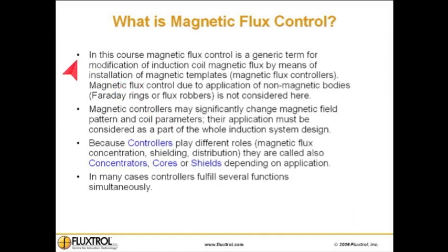Welcome to this section on magnetic flux control. First, what is magnetic flux control? In this course, magnetic flux control is a generic term for modification of induction coil magnetic flux by means of installation of magnetic templates, or magnetic flux controllers.